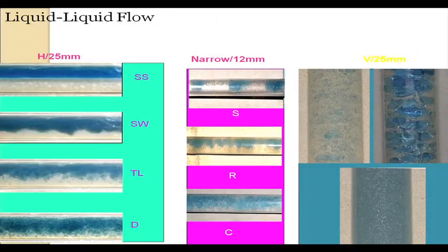Now, here I have got a very important point to tell. While we were discussing gas liquid flows, repeatedly I have been telling you that, well, when there is less gas and a large amount of liquid, we have bubbly. When we have large gas and less amount of liquid, we do not have droplets, we have annular. Why? Because the liquid phase can wet the pipe wall, the gas phase cannot wet the pipe wall. But when we are having two liquids, either of them can wet the pipe wall. It depends upon the hydrophobicity or the hydrophilicity of the pipe, which phase will have a greater tendency to wet the pipe wall, but you must remember that either of them can wet the pipe wall.